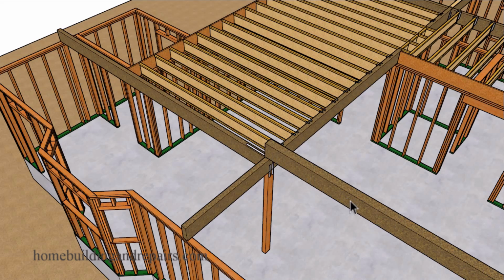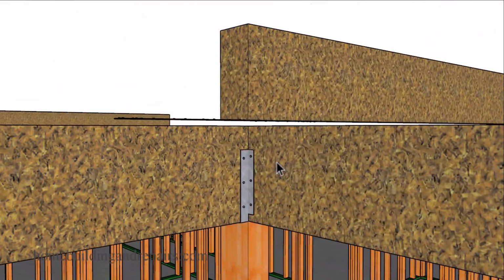Now, if we take a look at this beam here, it's basically going to tie into this beam to create some type of a structural drag in the same way that we will be using this beam here to connect the back of the house from the front of the house. We can use these beams here to connect one side of the house to the other side of the house. And by doing that, we can use some type of a strap to connect the beams together.